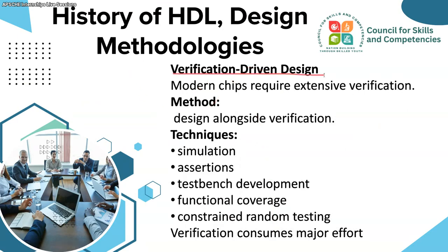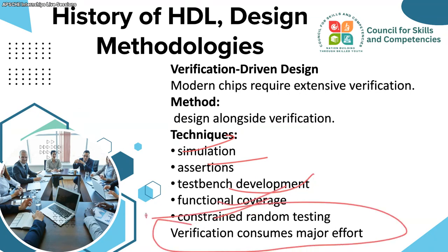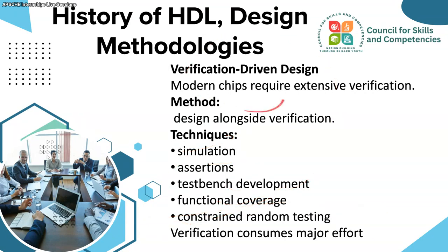Verification-driven design: modern chips require extensive verification, so we design with verification alongside. When we are designing, we start verification too. So simulation, assertions, testbench development, functional coverage, constrained random testing; verification consumes major effort.